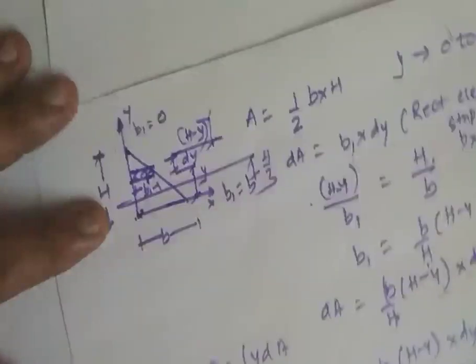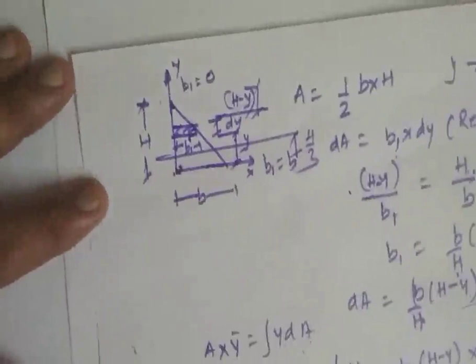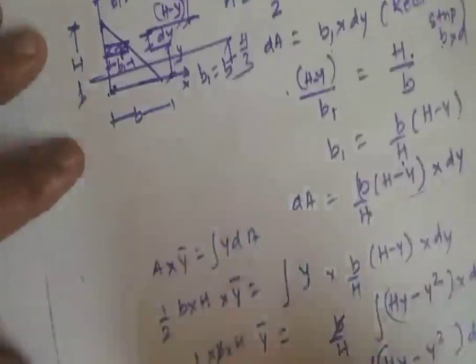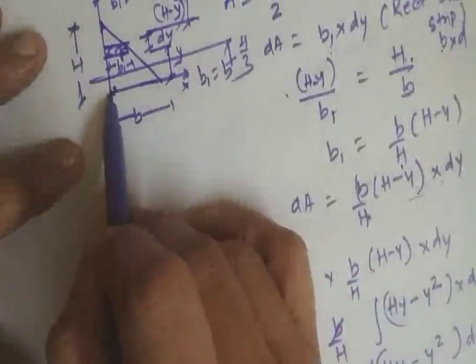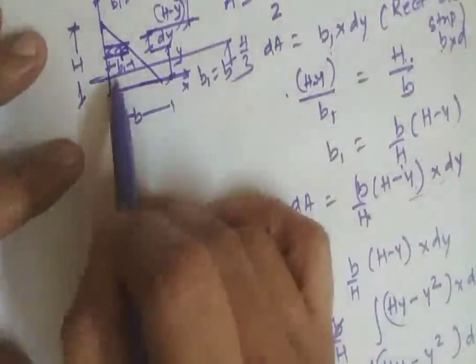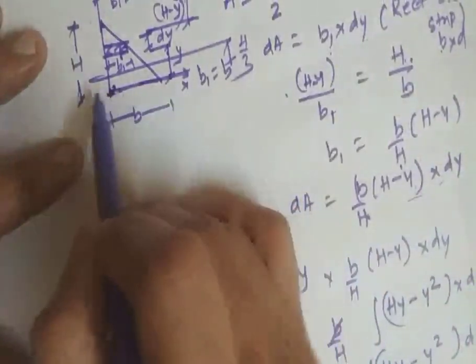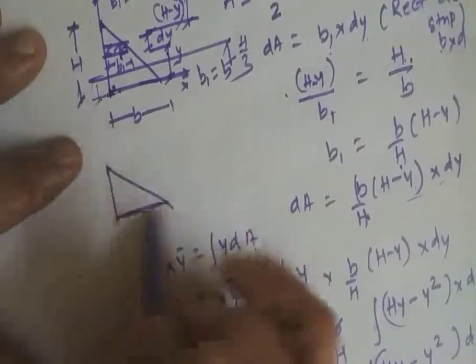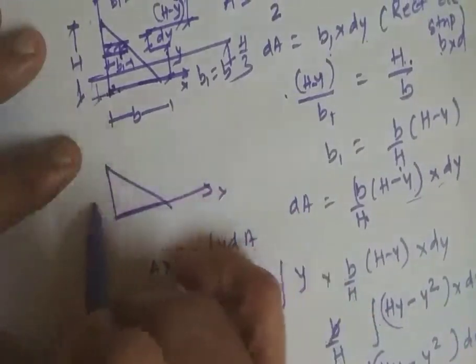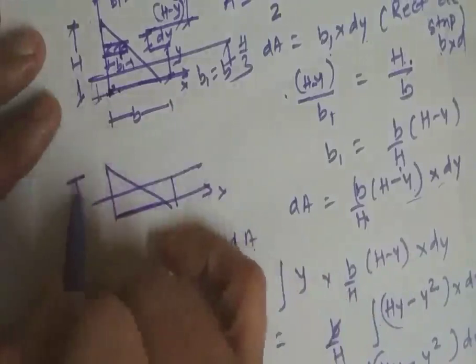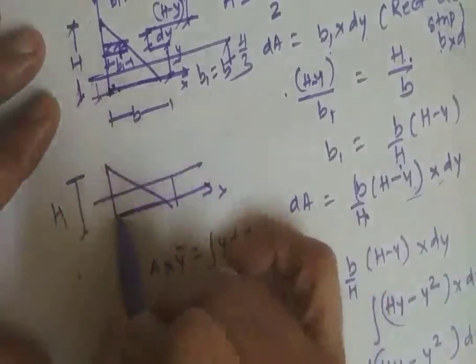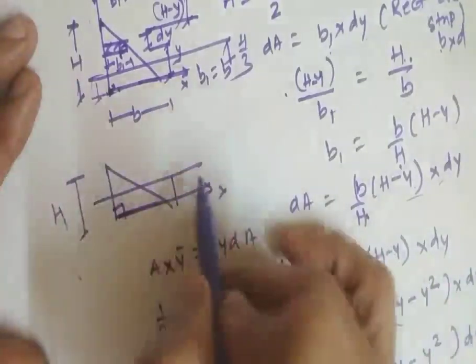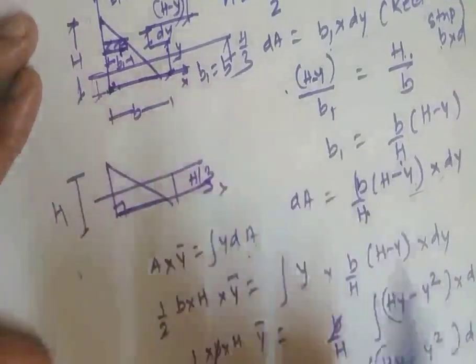That is the value of the centroid placed with respect to the base of the axis. Why with respect to the base of the axis? Because the x-axis and y-axis have been drawn with respect to the origin. So from this particular location, if you redraw the triangle again from the horizontal x-axis, vertical, the total height is h, and from the origin, that is from the 90 degree angle, the centroid distance is h by 3.